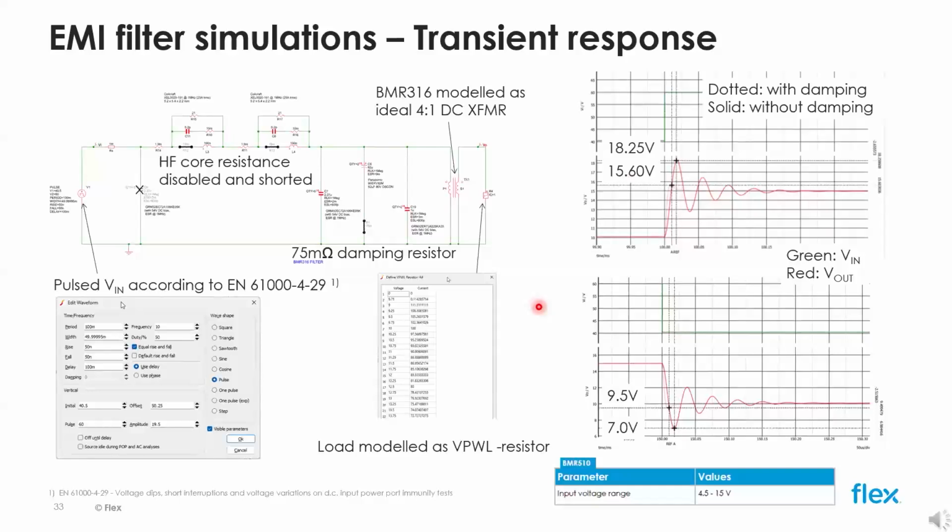Well, we shall take those simulations with a grain of salt. First, I'm driving the converter to the maximum input voltage. This is a bit unrealistic, as only an overdamped system would pass the test. Typically, voltages above 55 to 57 volts are not operational for this type of products.